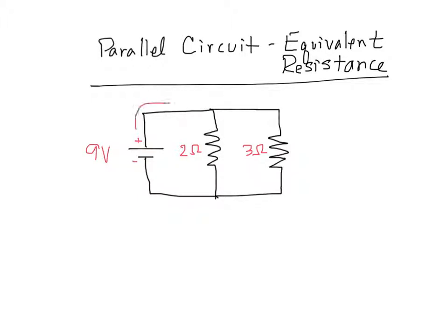So we've got I1 that comes through the top, comes to a junction right here, and I could have I2 here, and I could have I3 going this way. So I know that I1 splits into I2 plus I3. Okay, well, it's useful to think of this battery as having 0 volts on the negative side and a positive 9 volts on the positive terminal.